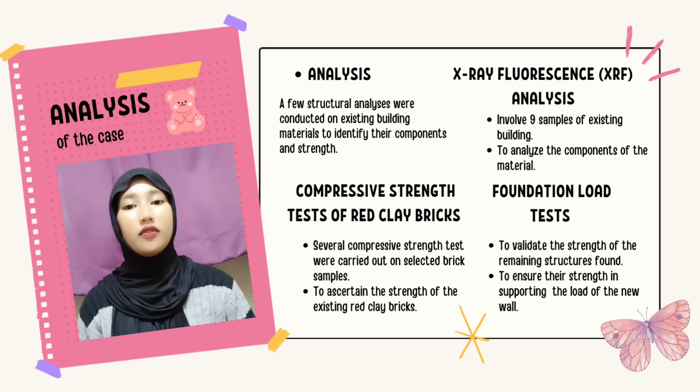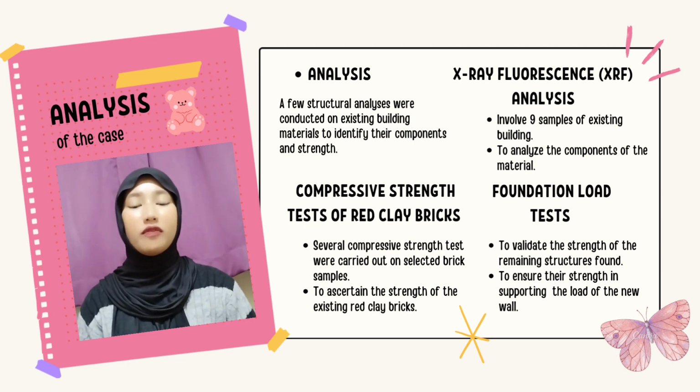Throughout the excavation work, the old fort foundation was found embedded about 1.5 meters beneath the ground. Results showed that the total residual settlement taken from 6 different load tests ranged between 0.7 mm and 3.36 mm.